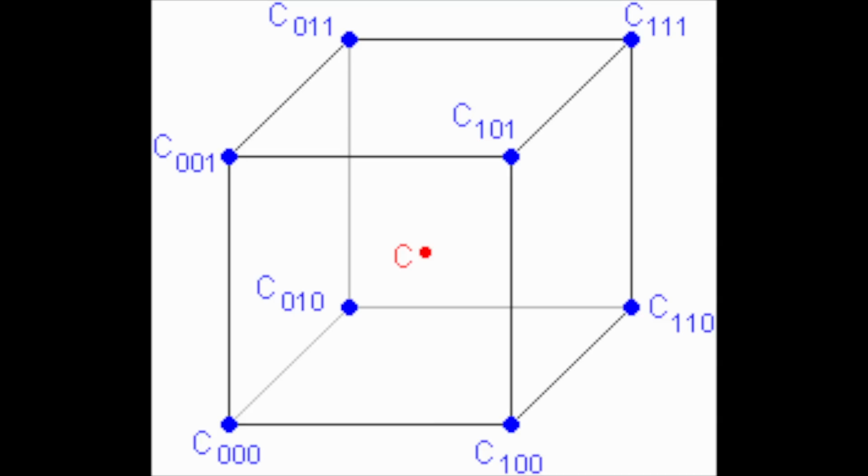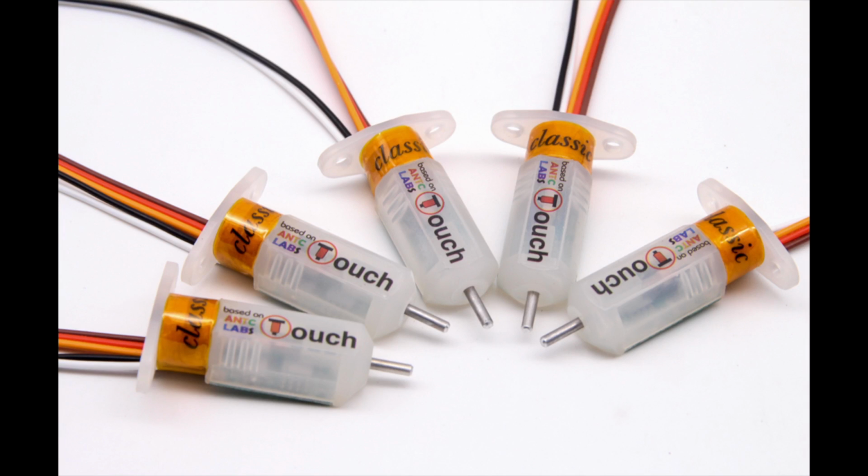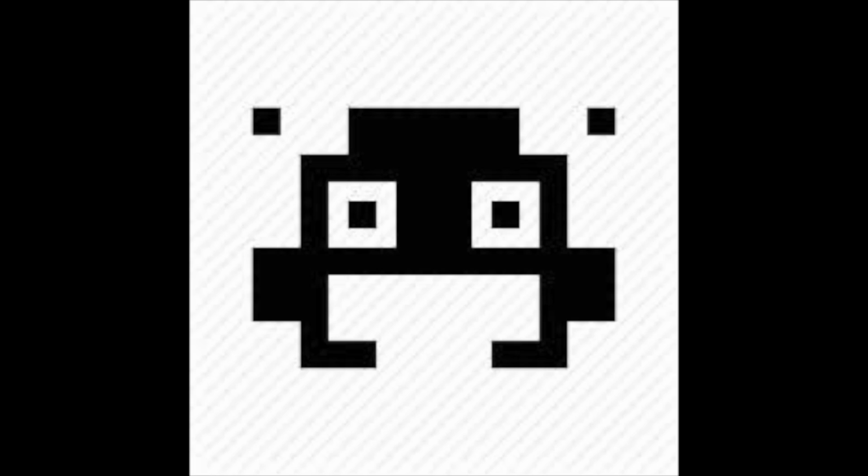So to give you an idea, you can peruse that video, skim through it, and say, okay, well, there's 6 different types of bed leveling. Do I want the one that draws a really fancy mesh and then does a whole bunch of interpolation to extrapolate data points and saves that in memory, and how much debugging do I need? And also other things like the BL touch sensors, they use up a huge chunk of memory. Graphical LCDs, those libraries involved use a huge chunk of memory. Do I want a custom splash screen? Do you need all that? Well, not necessarily, but you might want it.